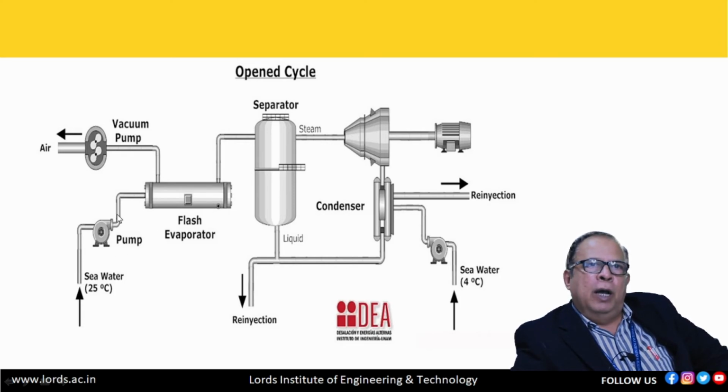When the seawater at 25 degrees centigrade is sent into the evaporator, it will be flashed into steam, that means wet steam will be produced here because of the vacuum. Because the pressure drops, and we know that temperature is related to pressure. So when the pressure inside the evaporator is less, the seawater will boil and become steam. That steam is sent into the turbine.